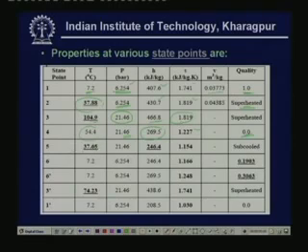Then point 5 is nothing but the exit of the liquid suction heat exchanger on the liquid side. This we obtain using the energy balance, as I have already explained, across the liquid suction heat exchanger. So, we find this enthalpy from the enthalpies of H4, H1 and H2, because the enthalpy differences for the hot and cold streams are the same. This works out to be 246.4 kilojoule per kg, and from the pressure value and enthalpy value we can find out the temperature and the entropy, and this is in the subcooled region.